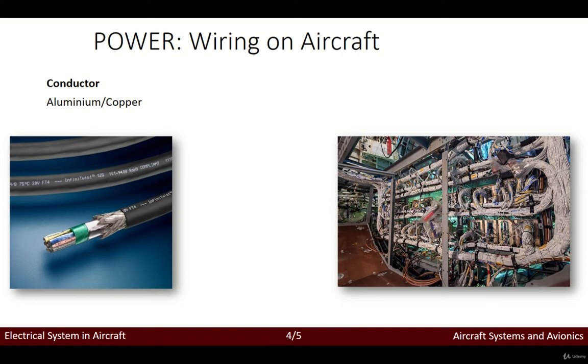So it's always a balance on the weight, and a balance on the amount of conductivity that we have on the type of conductor, okay? In the design of an aircraft, you just have to take into account usually the 2 possibilities, using aluminium or copper, and you should also take into account the technological inconvenience that might be related to each one of them, okay?